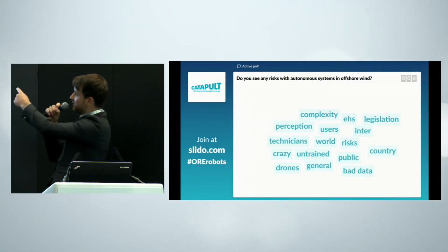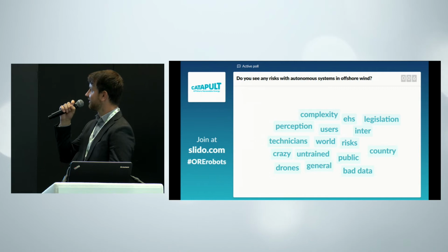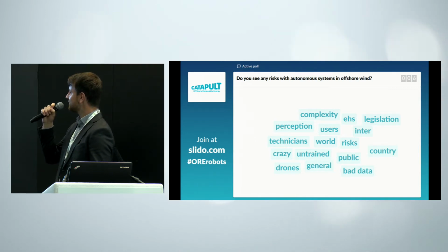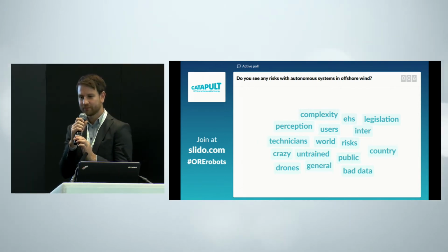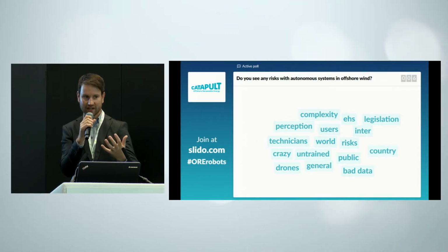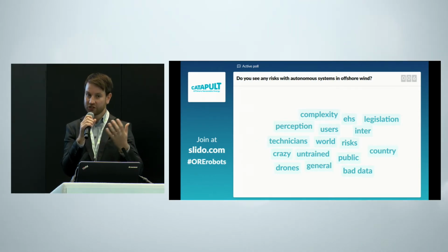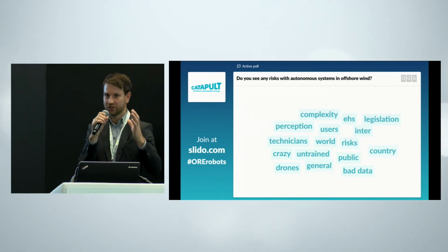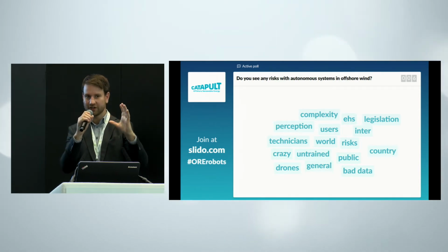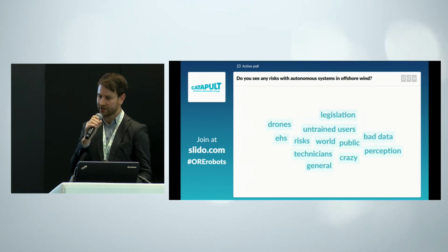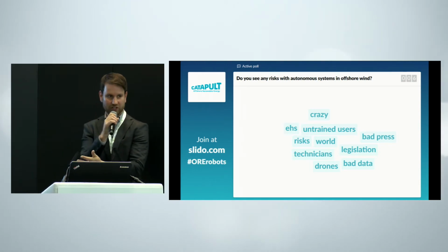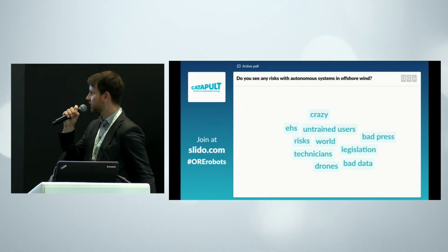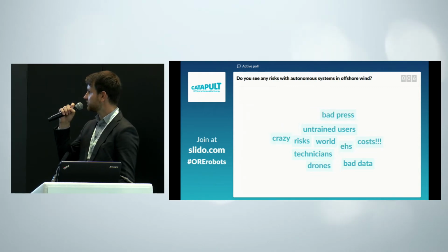Okay, great. So we've got more coming in here. Let's see. Someone's just written risks, which is great. Risks are risks. Maybe elaborate on that one. Bad data. Yeah, so that's a good one. So you're trying to basically go out there, perform an inspection to the same standard as going out there with a human. Say we're doing a blade inspection, that human can get very close to the blade, take a very good picture, and that gives you confidence. Now you need to be able to replicate that with a UAV. The technology is no good, no matter how much cheaper it can be, unless you can produce the same quality of data. So that's a good one.